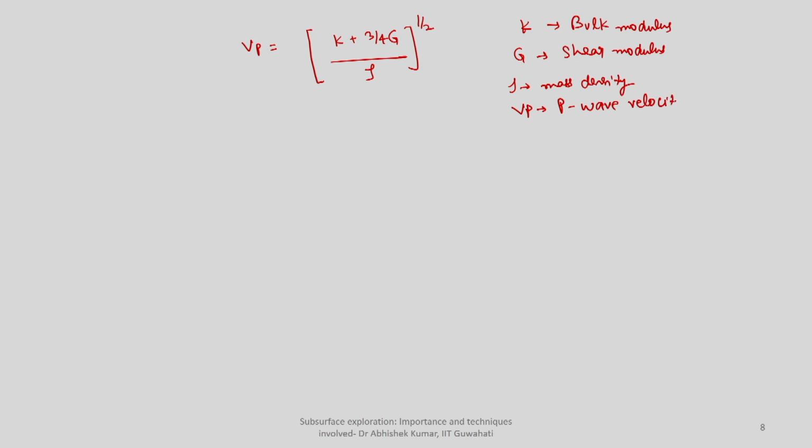In the same way you can quantify shear wave velocity, because the shear wave causes disturbance in terms of shear, like shear failure. So it is directly related to your shear wave velocity, Vs, the S wave velocity. In the previous table I gave you the range of primary wave velocity for different media. In the same way you can determine the shear wave velocity of the medium.